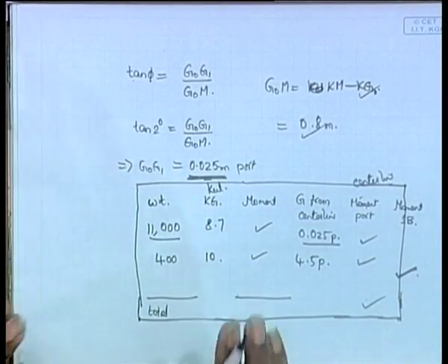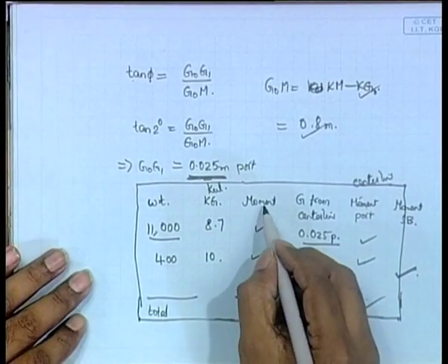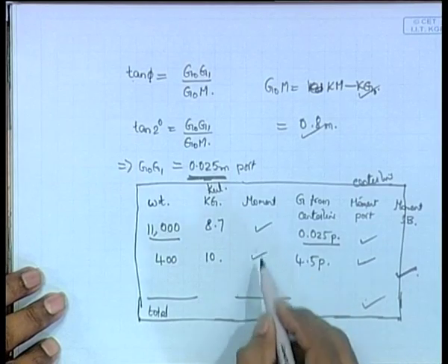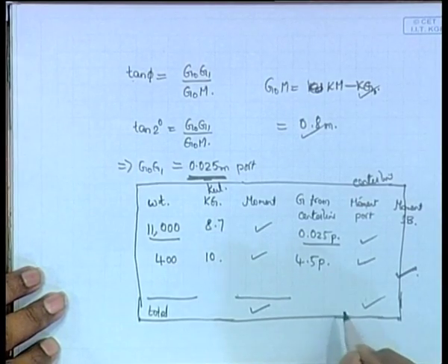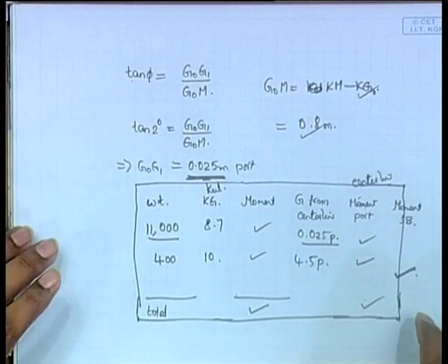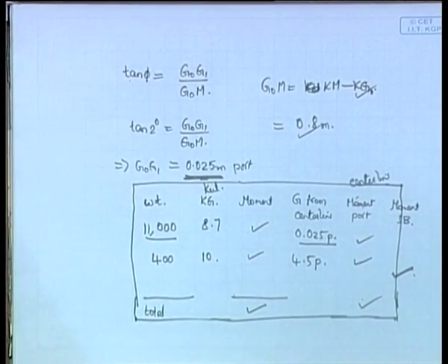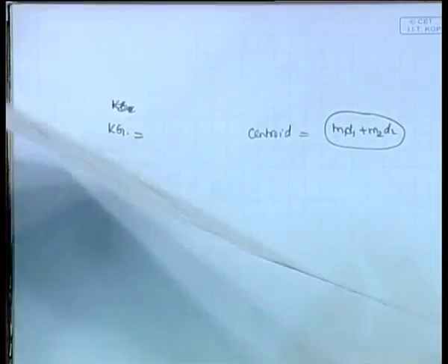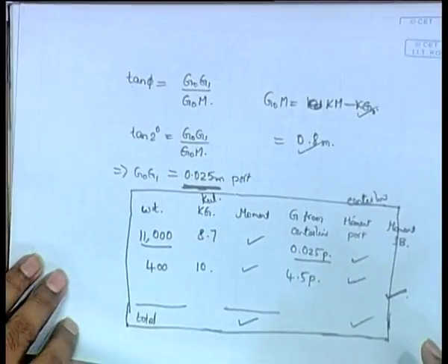This total weight is after all the loads have been added, and you have the total moment here. This moment is to find the KG. That means you have weights at different points, and you are just finding where the net acts. So that is KG at different points. This is just to find that KG, and this is actually what you are thinking of. We are talking about real moments. It's a vector in that sense. One moment is causing it to heel like this, one moment is causing it to heel like this. We are finding the summation of that, and that much moment is the net heeling to the starboard or to the port side. That's what you will actually see.